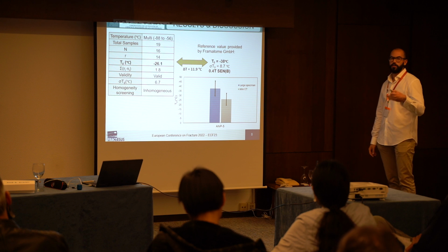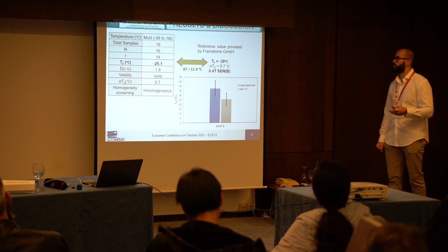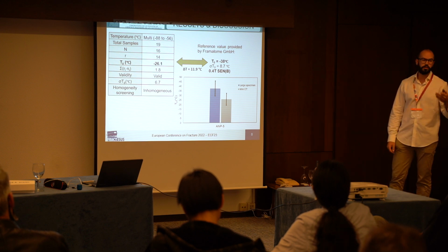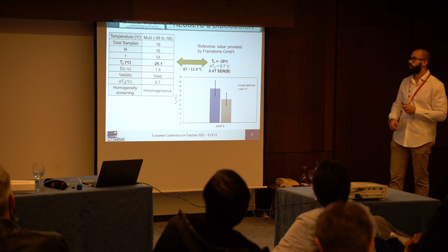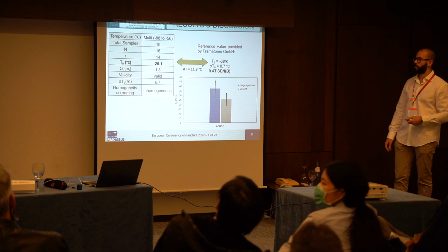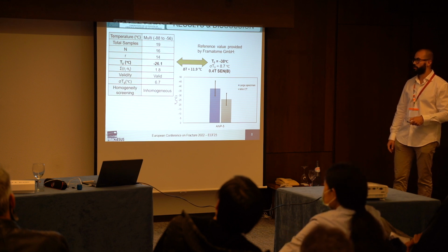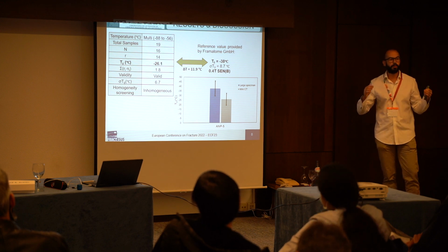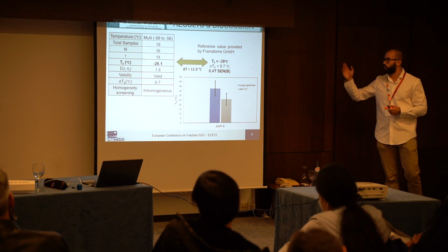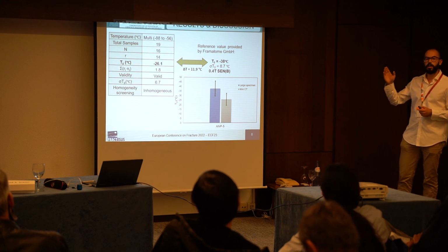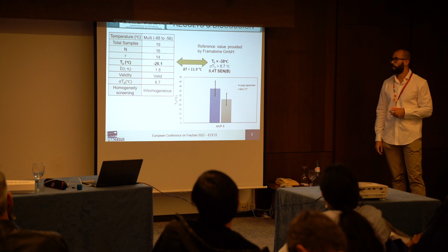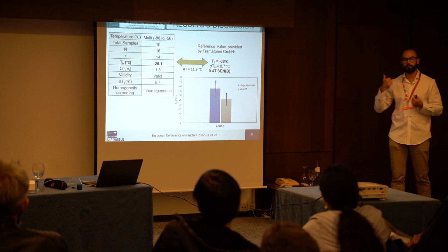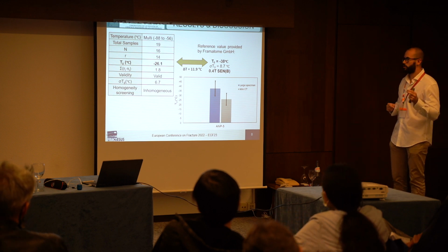We have employed a multi-temperature methodology for this material. We obtained the reference temperature of minus 26.1 with a standard deviation of 6.7 degrees. Of course, this material is a weld metal, so the result is inhomogeneous. The reference value provided by Framatome in this case was a T0 of minus 38 degrees and a deviation of 8.7 degrees.